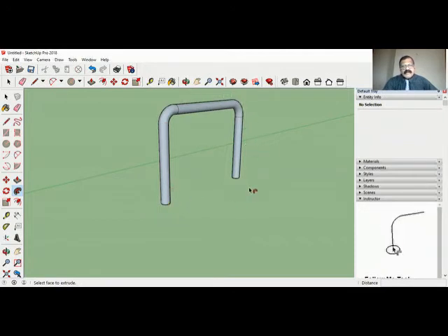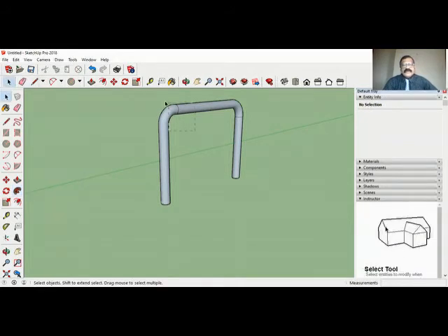First you have drawn a path, then you have drawn a section. These lines you can remove. What you do is you cross select this, press shift and deselect these two, so you get only this item. Go to entity info, make it soft, so it has gone.